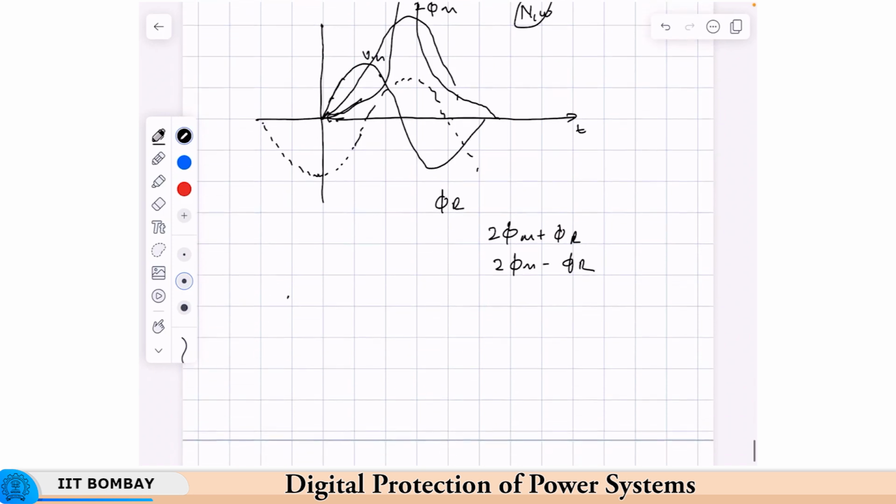Now, as we said, this can happen in 2 or 3 cases rather. One is, of course, when initially the transformer is energized, initial energization. Two, there could be a temporary dip due to faults. If there is a three-phase fault, say just after the transformer, and that is cleared, the voltage will recover from almost 0 back to normal voltage, and that is known as a recovery inrush.